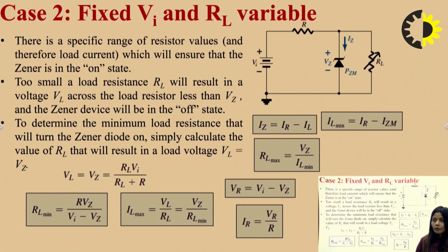As I discussed earlier, while doing Zener diode questions, you need to find out whether your Zener diode is forward biased or reverse biased, whether it is acting as an ideal component, or it is active, it is on, or it is working as a battery, a fixed VZ battery. So here we need to find out the state, and then the rest is very easy for you.